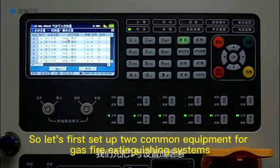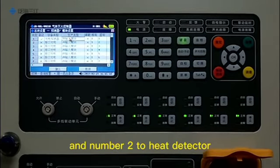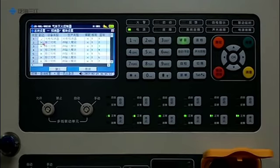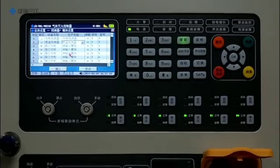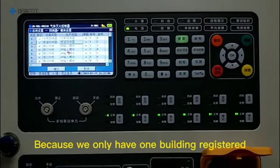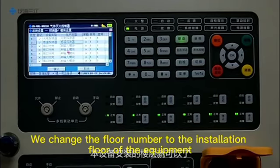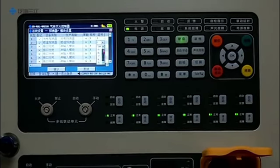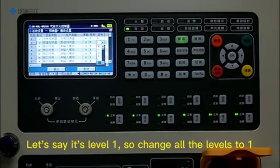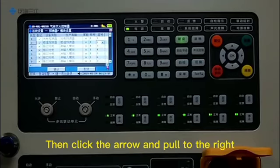So let's first set up two common equipment for gas fire extinguishing systems. Let's set number 1 to smoke detector and number 2 to heat detector. Then it is the building number and floor number settings. Because we only have one building registered, we do not need to change the building number. We change the floor number to the installation floor of the equipment. Let's say it's level E, so change all the levels to E. Then click the arrow and pull to the right.